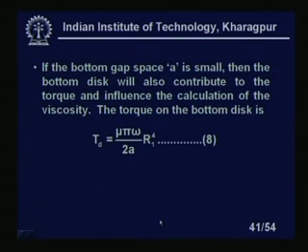If the bottom gap space is small, then the bottom disc will also contribute to the torque and influence the calculation of the viscosity. Usually it is small.